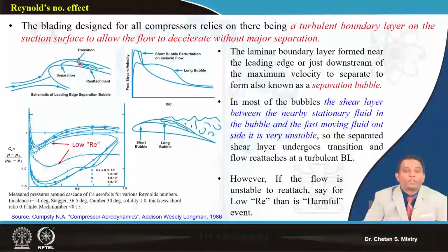Because of the presence of that, in the later part we will have early transition, and in the later part our flow will be turbulent flow. So here if you look at, this represents two different shapes of laminar separation bubble. We can have a smaller laminar separation bubble, and we can have a larger separation bubble, extending from 10% to almost maybe 70% of my chord.